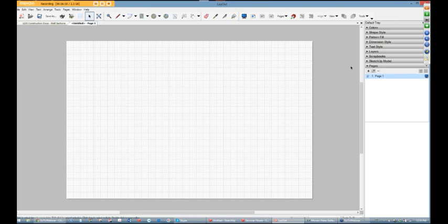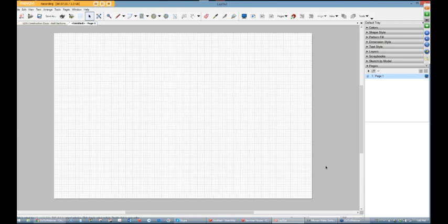Well, firstly, you can't import CAD into SketchUp or into LayOut, but secondly, you can't edit that import, because really all it is is an image file that you're going to bring in. So if you were to import something from, say, CAD, it would be an image. So you'd have to convert your AutoCAD file to a JPEG. And then just keep in mind, you can't edit that. It's just an image. So I essentially don't recommend that. The idea here for me would be to draw your own title block.